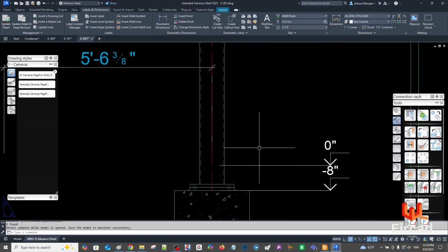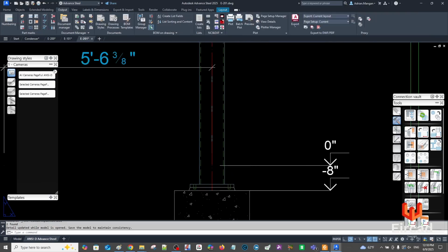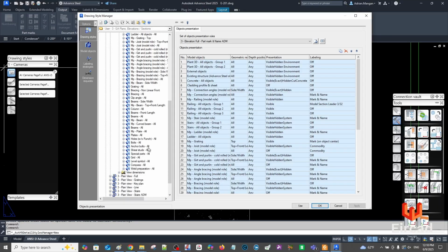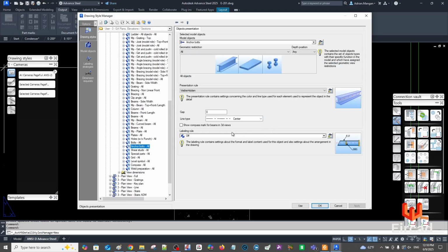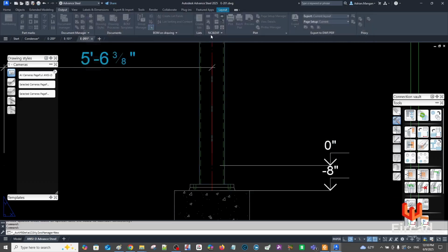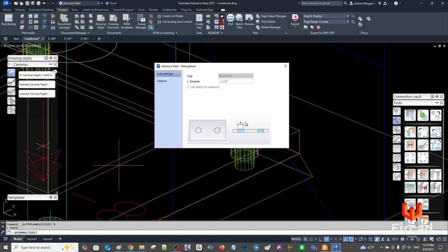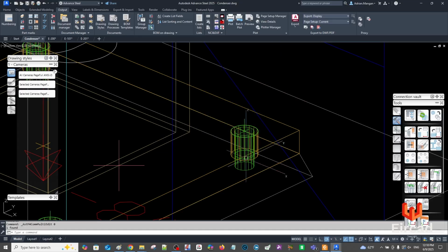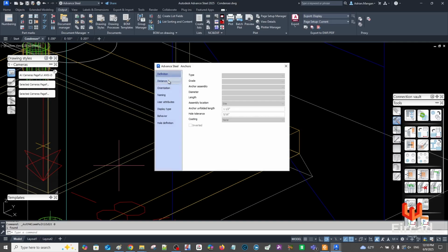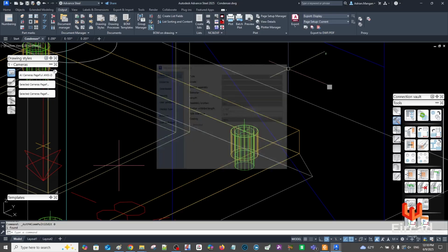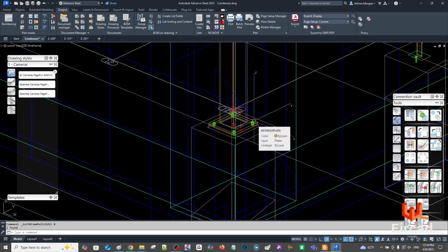You can see the other problem we have is we don't have any anchors. Obviously, you want to turn the anchors on. I don't know why they're sending them out with anchor bolts turned off. Like why are they visible, hidden? Oh, you know what? This could be another issue with anchor bolts. It is. These are anchor bolts that I created in the previous version of Advanced Steel, and now they're not available. That's why the anchors can't be seen.